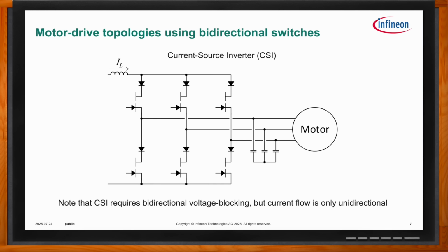It's also fault tolerant, meaning that if I have an open or shorted phase, I can still run the machine with reduced performance, kind of like a limp home mode. So these inverter systems are being looked at for aerospace applications or even automotive where reliability is really critical, and to be able to maintain some level of control over the machine even if you've lost a phase.